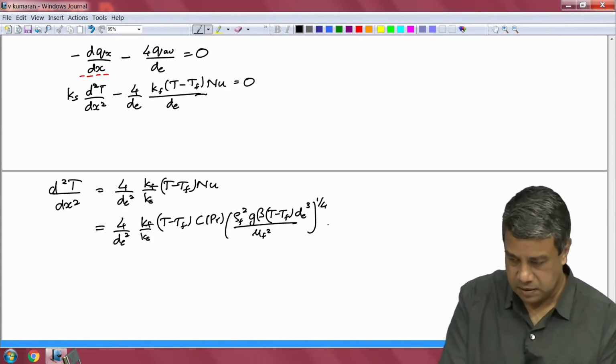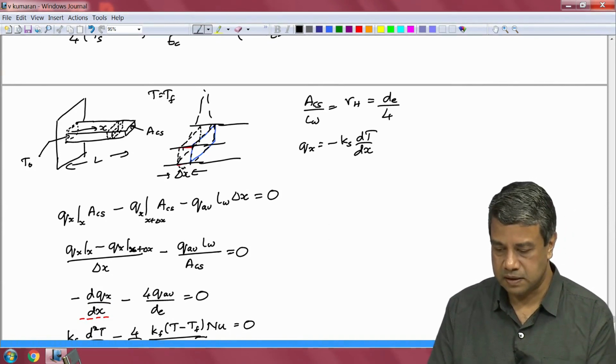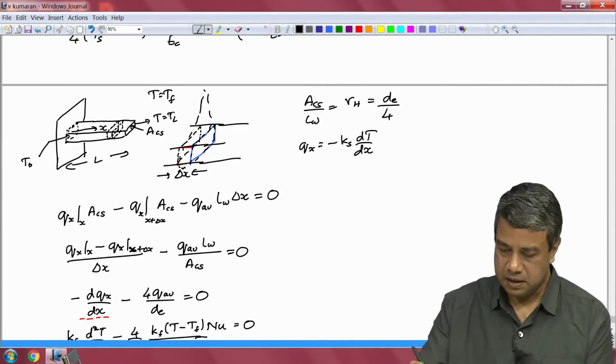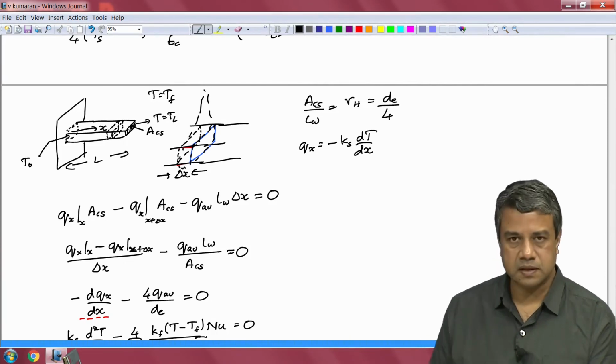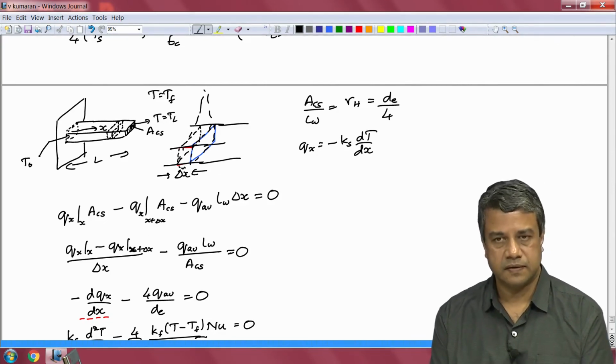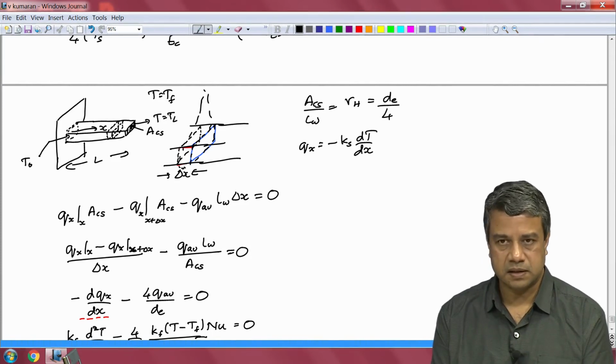That is, you know that the temperature at x equal to 0 is T naught, and you assume that at the other end of the fin T is equal to TL, okay, and I will assume that the temperature gradient at the other side is 0 because there is no flux coming out of the other side. It is an insulated end of the fin, okay, on the right side, and that temperature is TL.